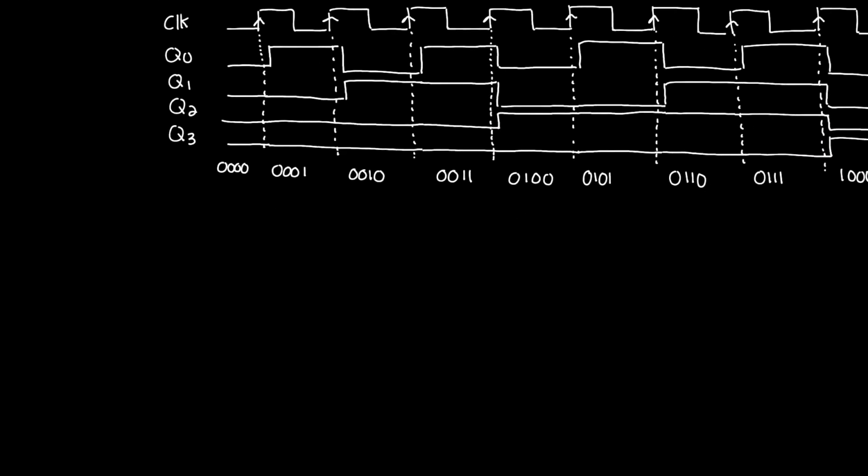So in fact, what I see is the same thing that I saw in a ripple counter. So just like in a ripple counter or an asynchronous counter, the frequency of the most significant bit output is equal to the frequency of the clock divided by M, which is the mod number. And again, the mod number is basically, think of it as just how many distinct states my counter has. So in this case, we're doing a mod 9. I have 9 distinct states, which go from 0 to 8 and then back to 0.